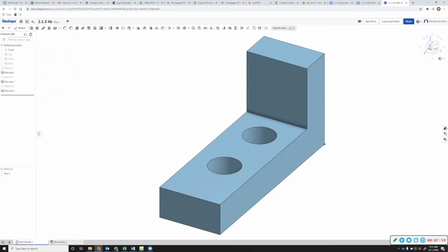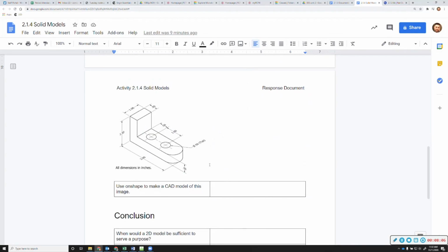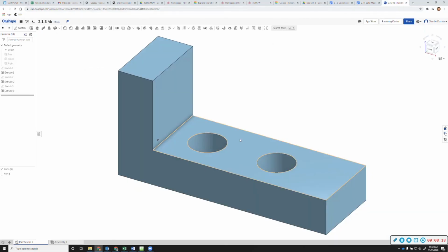Lovely. So if I click the other angle here on my view cube, and I look, are we exactly the same? Nope, we're not. We need to make this rounded edge here. And when you do a rounded edge like this in CAD, computer aided design, it's called a fillet. So we have to look up here for fillet. So this is our building tools. Usually the modify tools are next to it. Chamfer, fillet, F-I-L-L-E-T, not fillet like a steak, but fillet. It actually has one more L.